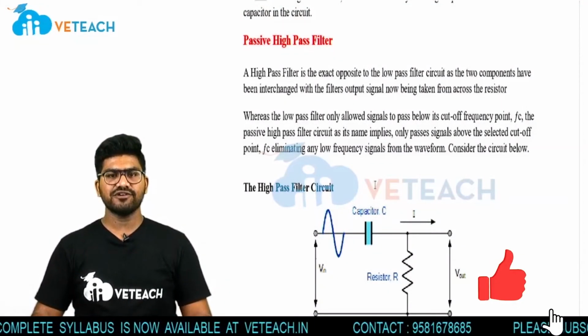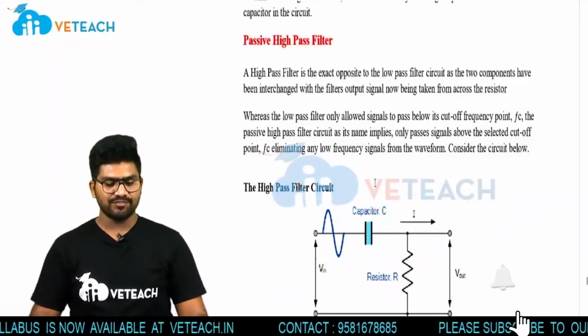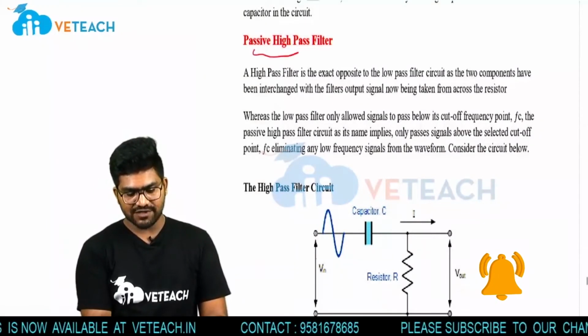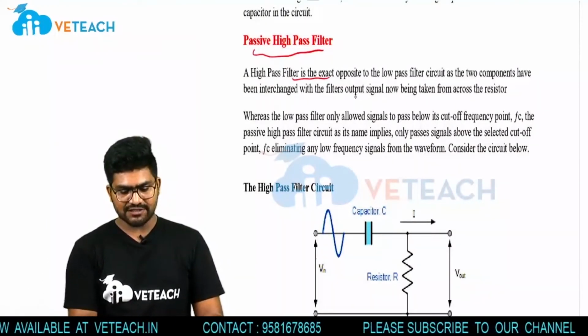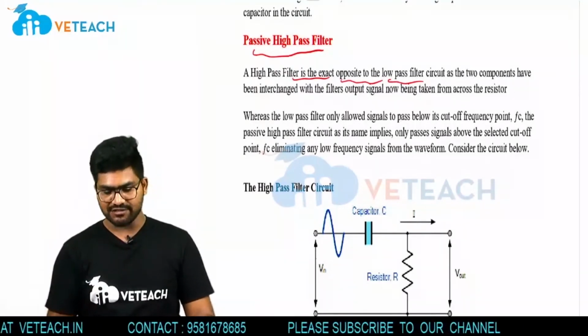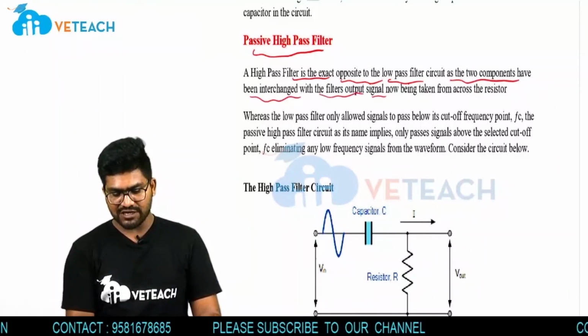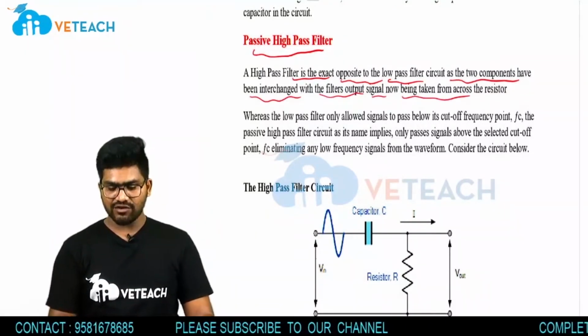In this session we are going to discuss the high pass filter. In high pass filter there are two types. The passive high pass filter we'll discuss first. A high pass filter is the exact opposite to the low pass filter which we discussed in an earlier session, as the two components have been interchanged, with the filter's output signal now being taken from across a resistor.